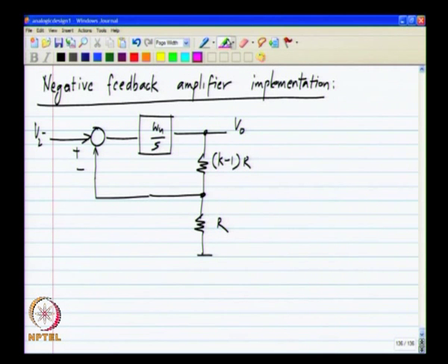So as you know, this is an amplifier of gain K and we have investigated its behavior extensively. To be able to implement this, we need to have a way to take the difference between the input and the feedback quantities and a way to integrate it. And this combination of taking the difference and integrating it, we know is the op amp or the operational amplifier.